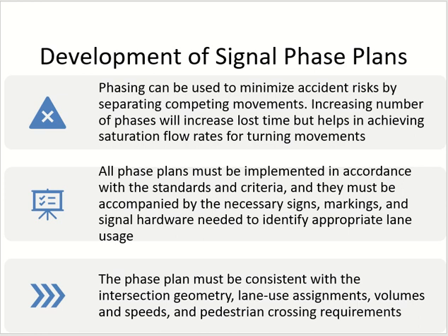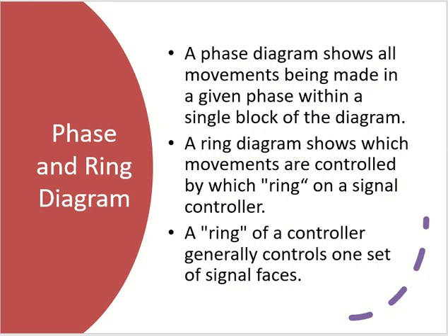Okay, you cannot have a separate phase without a separate lane. And if you are giving a separate lane, how will the drivers know? You have to put markings as well. You may have to put a signboard as well, a big signboard. If it is a more critical or high speed road, you may provide a traffic island as well. So all these things are happening because of what? Because of your phasing plan. You decided I want a separate phase for left turn, so now you have to do all these things. Clear? Okay, so design according to the phasing plan.